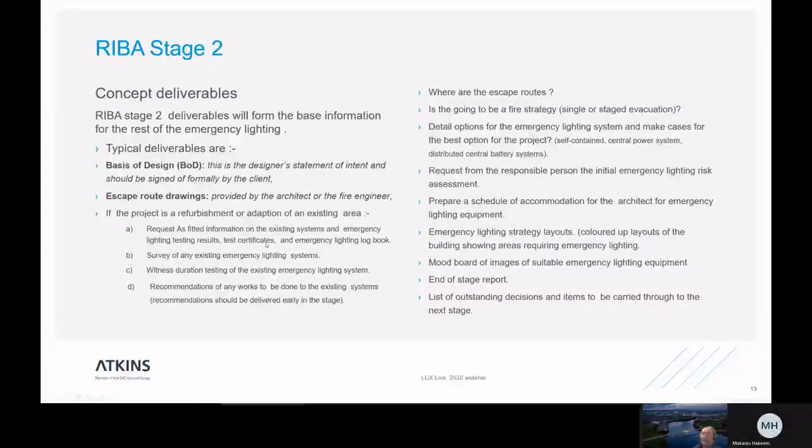And BS 5266 says that you should actually do a survey of the building and see whether it meets the standard, and say to the client, if there are shortfalls, how are you dealing with these shortfalls? Because if you are, say, required to actually just refit out a room or a floor in a building, that is not the emergency lighting for the building. The certificate is for the whole building. So therefore your design has to work with the whole, and you need to know what the whole actually is there. And that's very important. A lot of people don't pick up on that there.